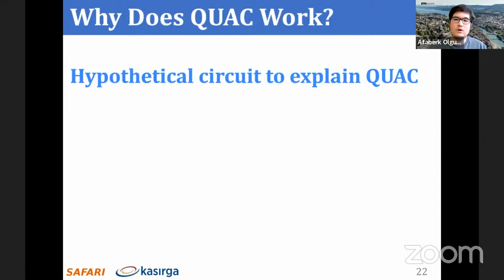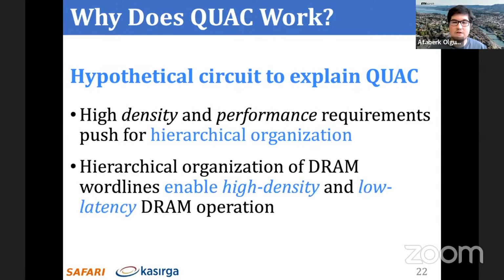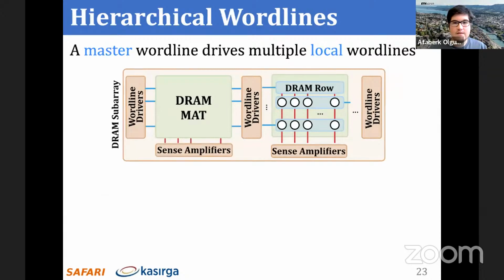To explain how QUAC might be supported in current DRAM devices, we develop a hypothesis. Our hypothesis is based on the use of hierarchical wordline schemes. These schemes are adopted in current DRAM architectures that have high density and high performance requirements because they enable high density and low latency DRAM operation. In this hierarchical wordline scheme, a master wordline potentially drives multiple local wordlines.